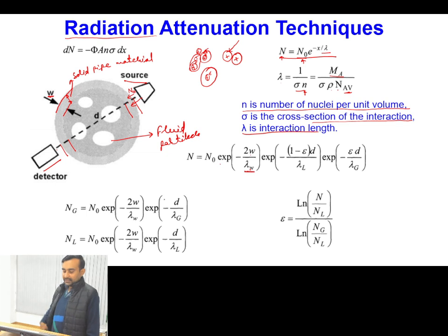Other than that, if the distribution is such that corresponding to this gas, the overall situation is nothing but my epsilon is the length of the gaseous phase divided by the total length, where the total length becomes the internal diameter of the pipe.